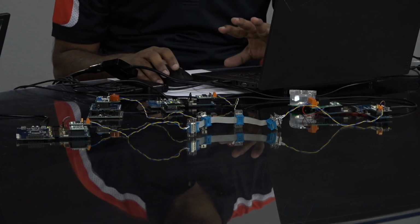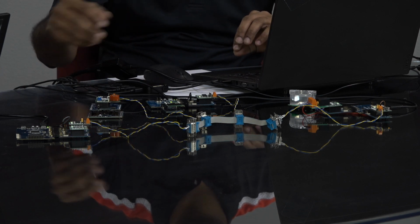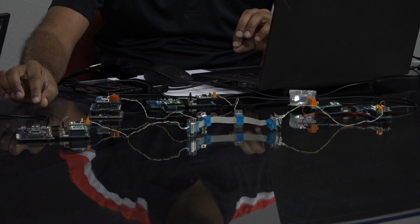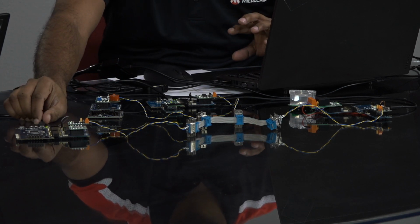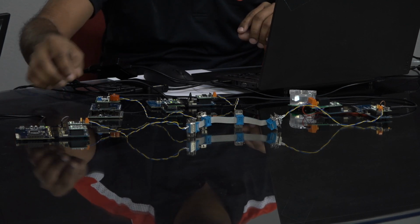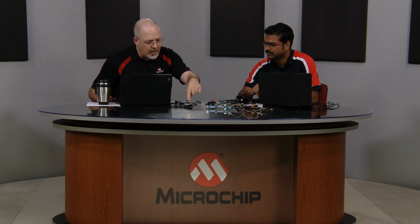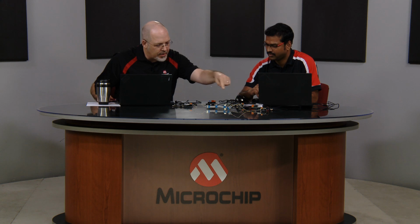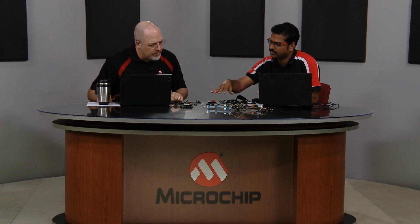Yeah, sure. This is a smart sensor node control system that I have built here. It is built based on the clickboard support, so we have all the clicks here. Each node has two different types of clicks, a sensor click as well as a communication click. If you look at each of these individual nodes, they have these CAN communication boards. Each node has a CAN communication board connected to the CAN bus, and it has its own sensors.